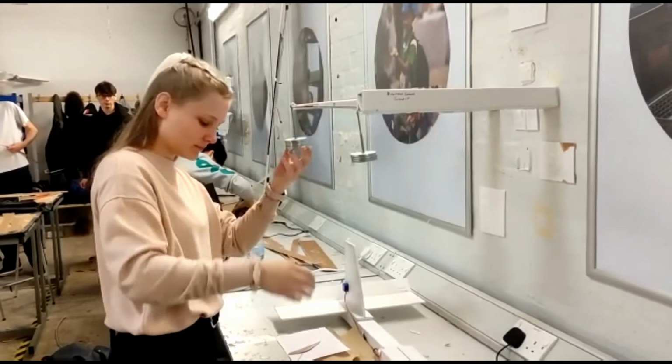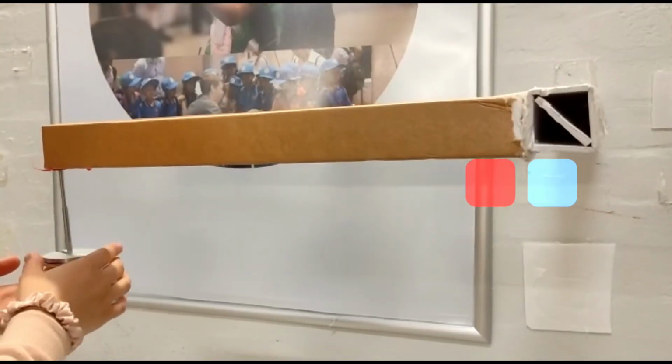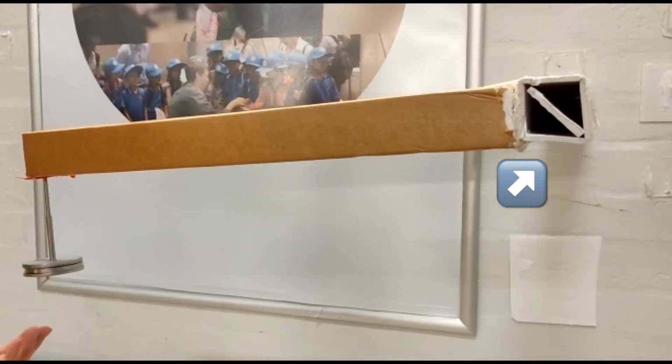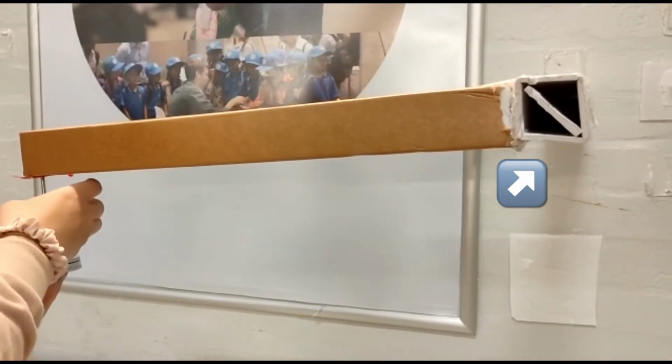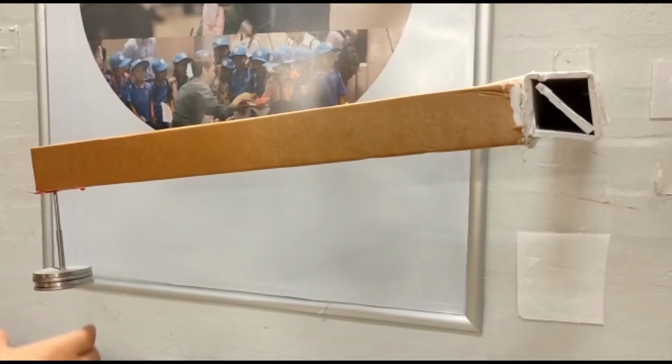These included direct stress and torsional compliance evaluations. We found in the torsion testing that the diagonal cross-section we had did not support the structure enough, so we changed to a different cross-section design.